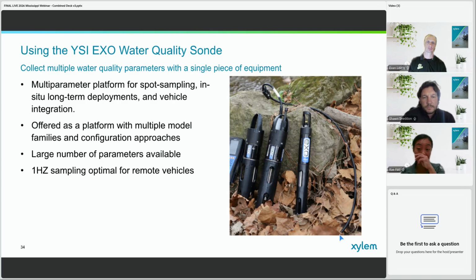That is a method you can use, especially on these larger rivers with higher flows, where you will likely have moving bed. With moving bed, you obviously don't want to be using bottom track, at least the raw values. You'll have a choice of either correcting the bottom track measurements if you do use bottom track for a ship track, or using stationary, or using GPS or GNSS for your ship track.